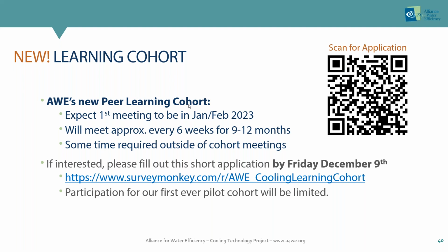I think it's a great thing for the cohort to address, because you can't just say up your cycles. It's going to depend upon local water quality. It's also a very hard thing to enforce. In the city of LA, the current code requires 6 cycles of concentration, but it's not what's happening in the field, and sometimes it's not possible. So I do think thinking about how we could best incentivize and mandate efficiency would be a great thing for the cohort to address.